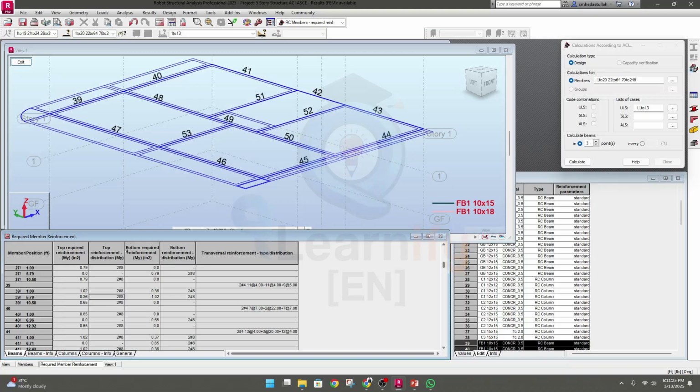Okay, so if we go for bottom reinforcement, this is the top required reinforcement actually. So you can see they have provided 2 reinforcement in the overall direction. Okay, but don't do it. I will check on this value, and then I'll go for a different design. They have taken number 8 bar to number 8 bar. Okay, so I'll not do it.